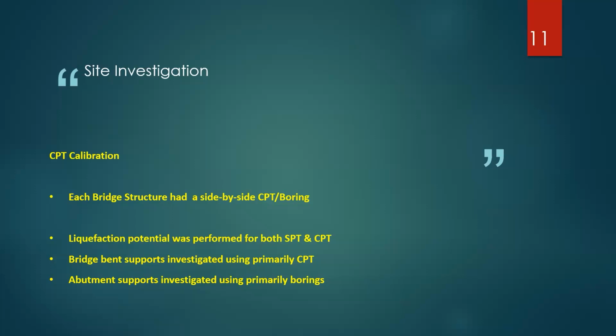So as I mentioned, I did talk about use of CPT primarily for design of foundations, but the focus was more at the pier, at the bent supports rather than the abutments. The reason for that was many reasons. This is a highly congested road. Traffic is on it all the time. So one of the reasons was construction, right? You want to have a lower footprint, lower impact on the traffic, and a lot of other elements that got into it. We focused on bents, primarily using the CPT, but in some areas we did the abutments as well. But primarily for abutments we were using borings.